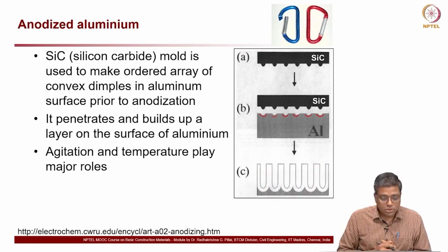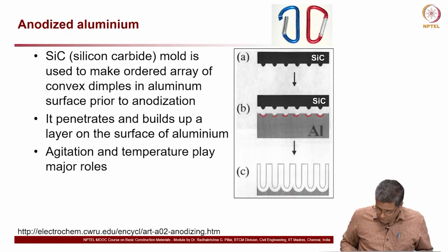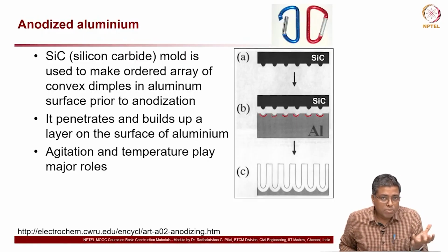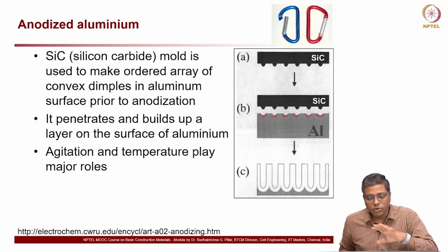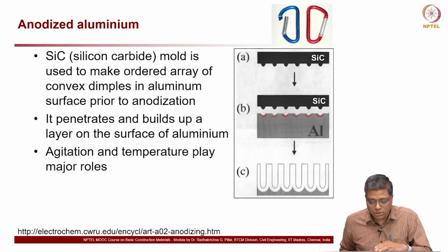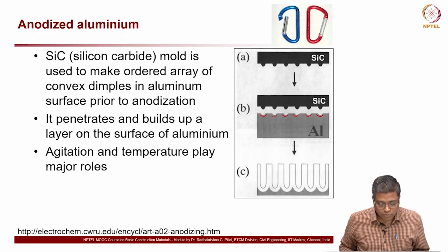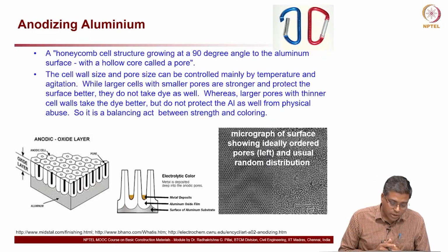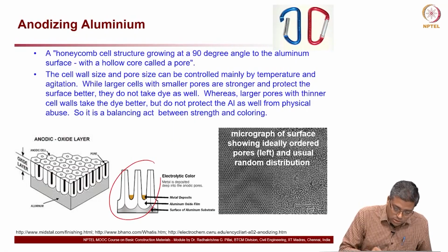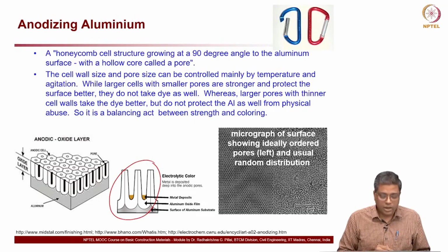So you have this oxide layer formed. Now the mixing process, or the movement of the dipping elements or the anodes in the solution, the flow of the solution around this thing, and the temperature of the solution play a key role in forming these oxide layers. So eventually, you can look at this, this is the oxide layer, the U-shaped layer which is formed.